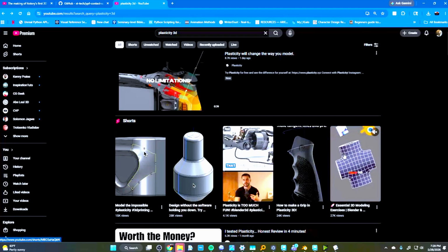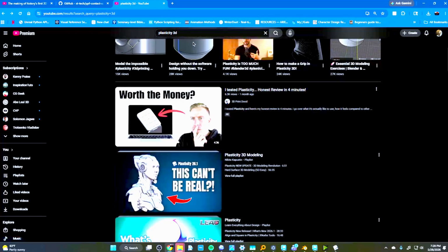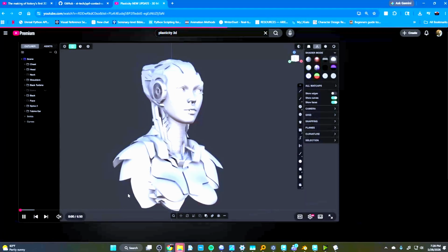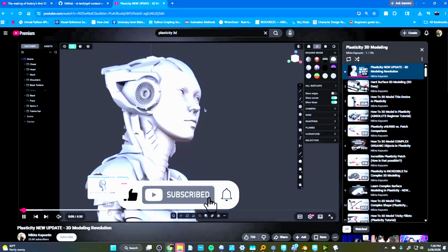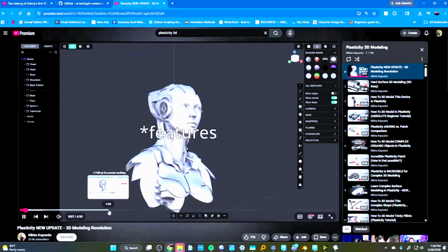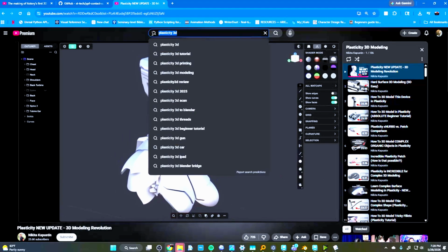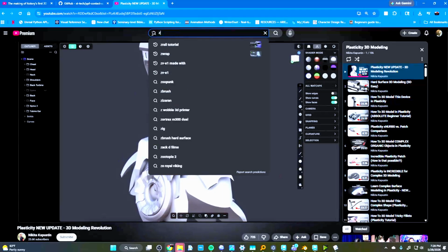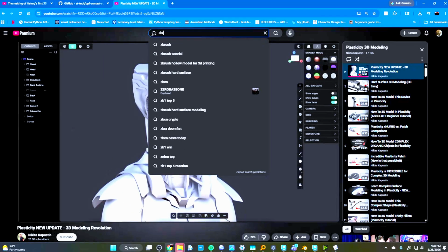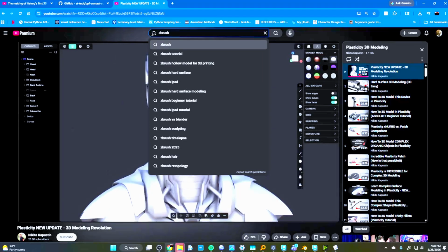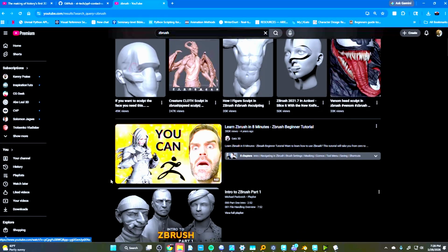And if you have a complex intersection of two shapes, and you want to take that joint and fillet that, it's apparently very easy for the solid modeling software to do that math. But if it's a mesh, it becomes very, very difficult because that shape has not been mathematically described. It's just a mesh. It's just a bunch of polygons. It gets very difficult for the software to figure out how to do what this user is asking me to do. Correct.